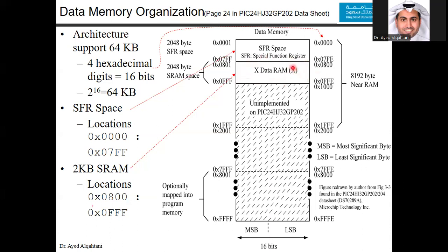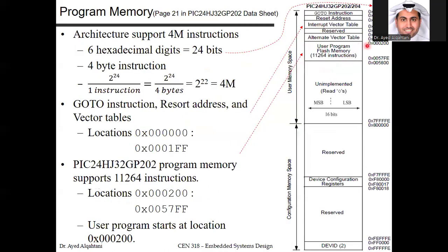If you want to store them in the first location of the memory, it will be in location 0080, and the next one, if the variable is only 8-bit, will start in 0081. And we will see this further in one of the simple programs in this lecture, how the variables are organized in the RAM, and also the code segment that we said will start here at this location.